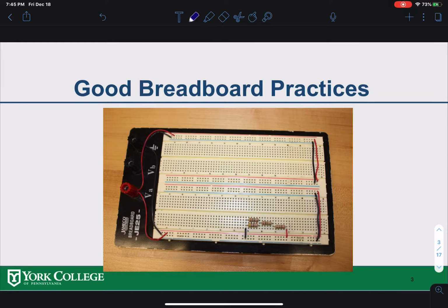So this whole rail over here is a positive voltage. This is the negative voltage over here, or reference. And on this side, positive voltage here, reference here. And also we made connection from here to here. So this rail also has the reference now, and this rail also has the positive voltage. And same here, this rail has the reference, and this is the positive voltage. So that means this whole breadboard on all 4 buses has the power supply now, and you can make a circuit anywhere you want. This is a very good practice. Nothing is jumping, nothing is making a loop on the breadboard. Very nicely laid on the breadboard.